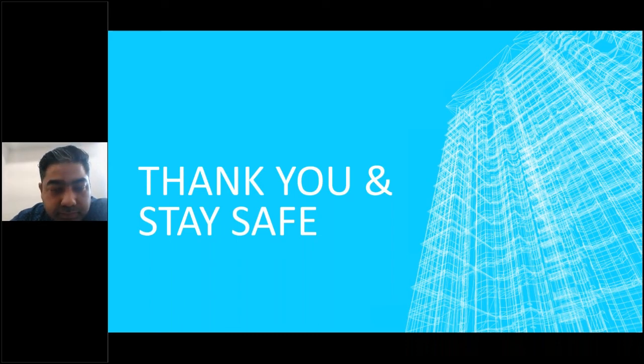Yeah, I believe that's addressed to me. So, smoke test, in the presentation I couldn't go into detail on that. I'm glad the question was asked. So basically, there are two ways we conduct the smoke test. One way of doing it is if you have no idea where the leakage is, then what you could do is use a smoke generator like the ones you see on the stage during a dance performance. You should be familiar with that.